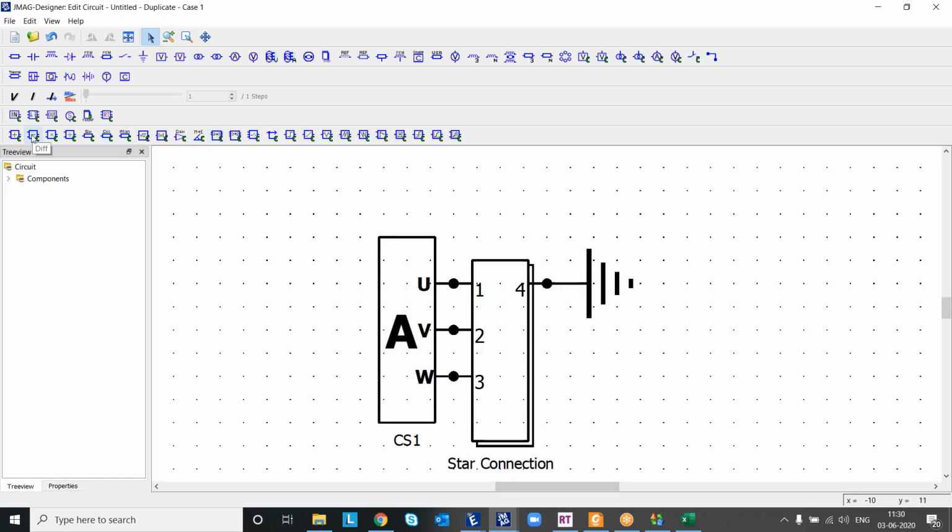And similar to that, we have many other options for different functions: we have sinusoidal option, cosine option, and like that we have many options. And we have switches, branches, steps, ramp. We have many functions for generating your desired circuit. And if you want to particularly design your circuit for any particular switches like IGBT or MOSFET, you can create a model using the Simulink option, which I have explained already, and you can input it into the MATLAB window. So this is how we can create a circuit.